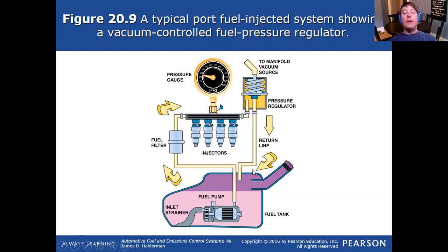Everything else is dumped back to the tank. And last chapter, when I discussed the importance of paying attention to that diaphragm ripping, you can see here nicely in the illustration, there's my cursor, where that little diaphragm rubber flap sits, and if it were to rip, on the other side of that, you have your vacuum.